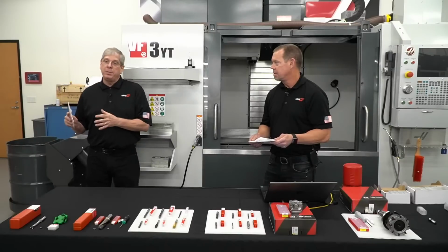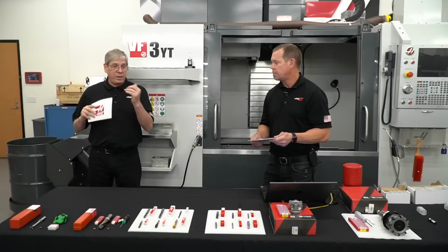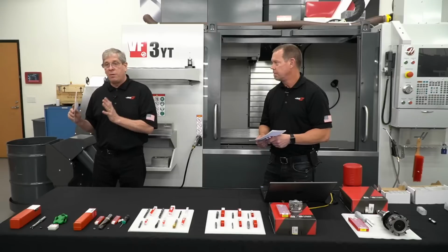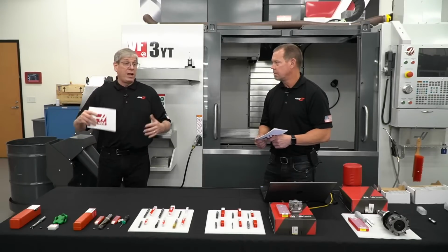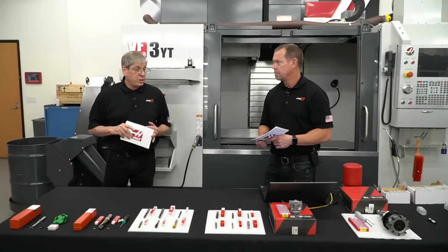So we got all the tools in. We set up a custom VPS template to define places for them to put the surface footage and the chip load and all the information that you would get from the manufacturer. We recorded via dprint statements to output the tool diameter, the material that we were cutting, a whole bunch of information that we all got in spreadsheets.